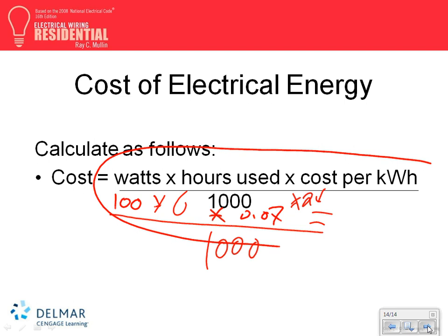Okay. When you were talking about this maximum number of disconnects, with my service coming into my place, are they talking about 6 services, 5 services? Or are they talking about "shall consist of not more than 6 switches"? Right, so 6 sets of circuit breakers or a combination. Yes, when my power is coming into the house and it's going into my box, that's what they're talking about. I can't have more than 6 of those, unless you have a disconnect.